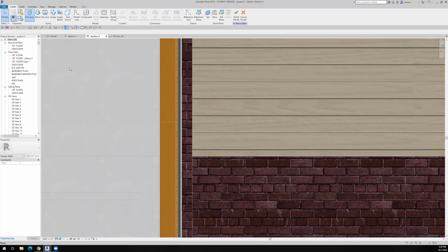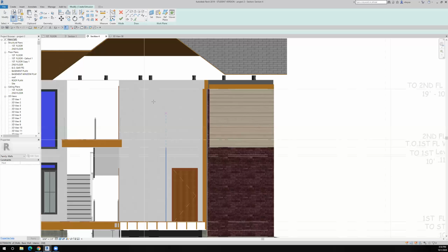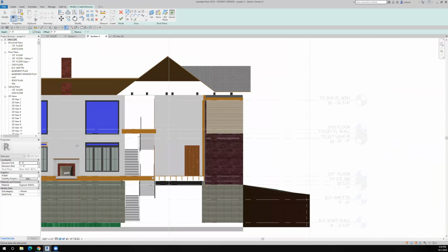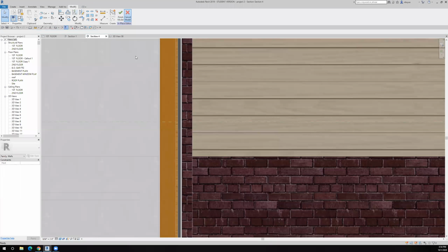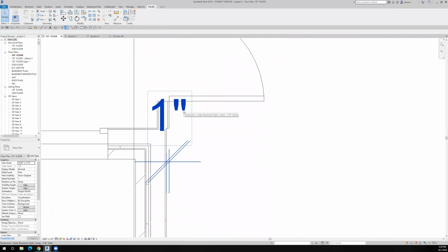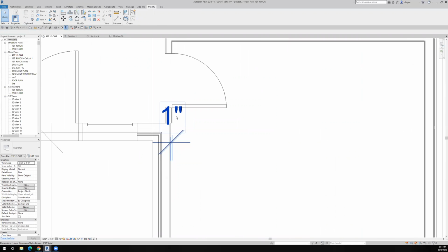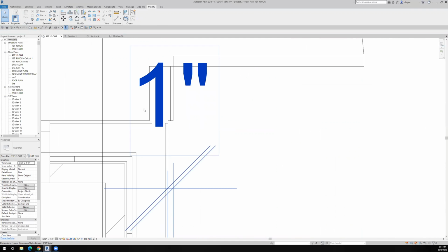We're going to do an extrusion. Revit says, tell me the plane you're going to start from. I'm going to try to pick this wall as the plane. If it won't let me pick any of these walls, and I'm having trouble picking that plane, so I'm going to X out of that, go back to the first floor, and I'm going to actually make a plane. So what I'm trying to do is put a plane right here.